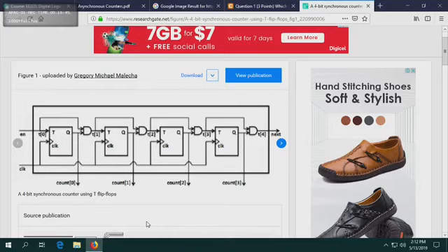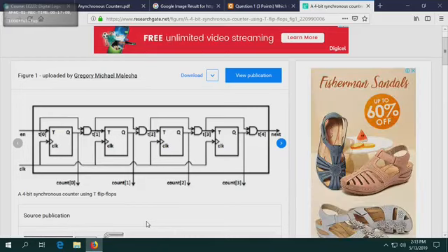Now, all of a sudden, you want to interrupt the circuit and make it go all to 0, or all to 1, or maybe make one of the flip-flops 0, one of them 0, all of them 1. You can't do that from your design because you've already designed it according to your state diagram. The next state will be what you have drawn in your state diagram and then the state table, and that's how you got all that big circuitry, the chunks of AND OR circuitry which you did in your project.